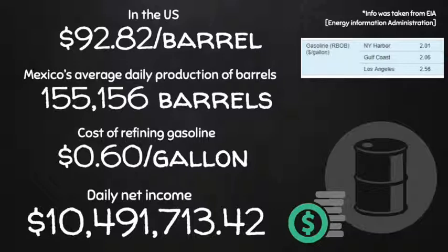The process employs either electric or turbine drives for the reactors and compressor to optimize refinery utilities. The operating cost for sulfuric acid alkylation depends heavily on reactor design, feed regeneration, residual contaminants, and the cost and availability of sulfuric acid regeneration.